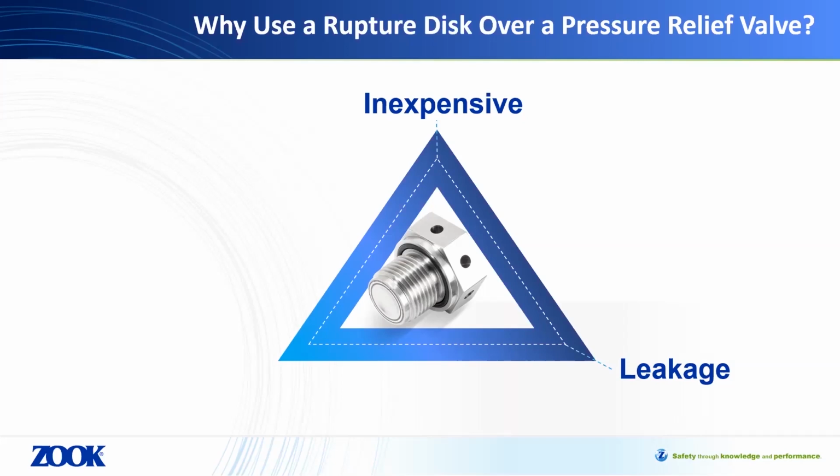Additionally, rupture discs, in some instances, are utilized in unison with a pressure relief valve. A rupture disc is a good solution to isolate a relief valve. They are a cheaper option than the valve and are commonly used to protect the valve from direct process exposure, prolonging the valve's life, and providing a redundant seal within the system. In this case, the rupture disc would be installed immediately upstream or in front of the pressure relief valve.